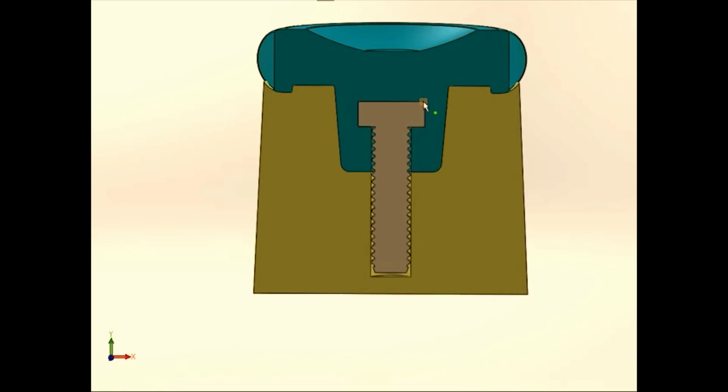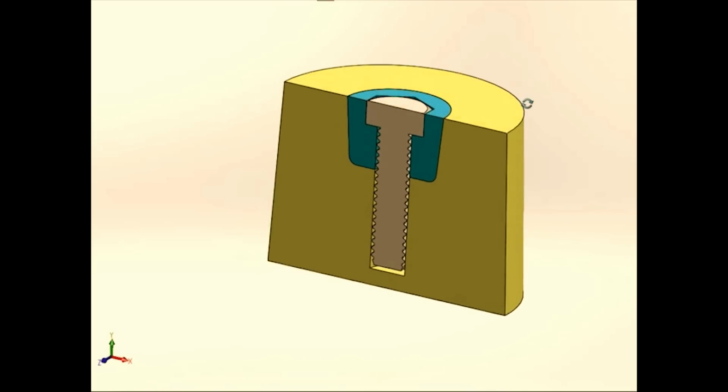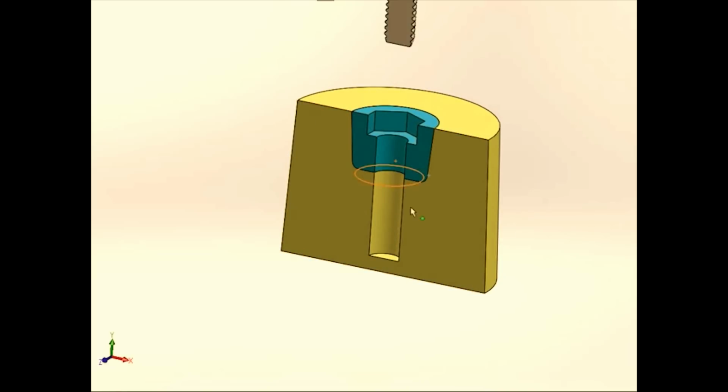And then once it gets up to this last layer here, it's going to start putting this model material on top of this screw. We're going to have to put a pause in there. So when it pauses, the build is going to look something like this without the screw. And so we'll tell the machine we want it to pause before it gets to this last cap layer. We'll open the door, come in with our screw, and we'll just press it right into place.